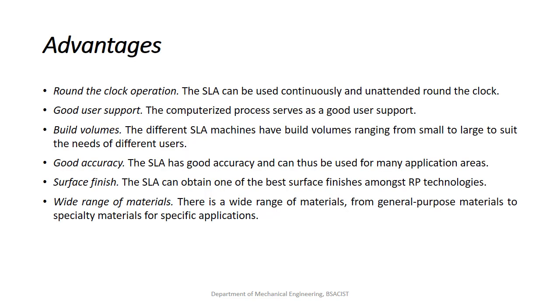So, the advantages. We can get round the clock operation. The SLA can be used continuously, unattended. Here the computerized process is well supported. We can achieve very good build volumes, from small to larger numbers of parts. Whichever the size of the container, we will be able to produce a part which is somewhat smaller than that. The accuracy is very good.